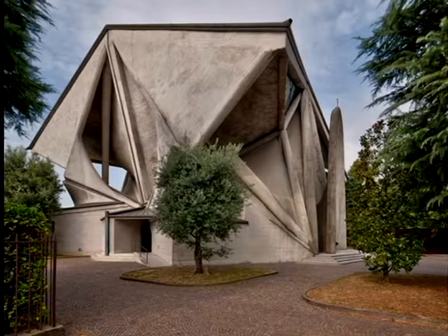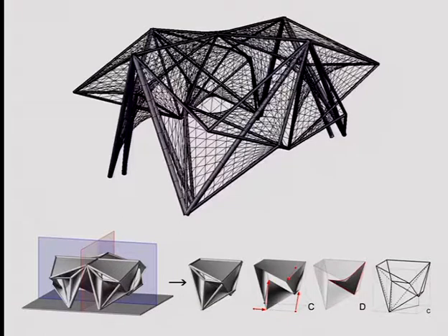So this is a composition of 20 hyperbolic paraboloids and there is a frame also that keeps them together. But I redid the geometry in Rhino, and that probably is a bit more understandable. So it's symmetric. So what you get out of it is that you divide it, you can mirror it twice, and then you get these 4 hyperbolic paraboloids plus 1. Here the cover is in the middle. And then there is a frame of 14 bars that keeps it together. Then double mirror, and that's the structure.